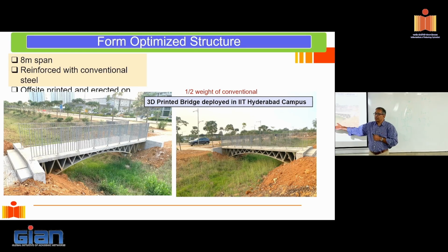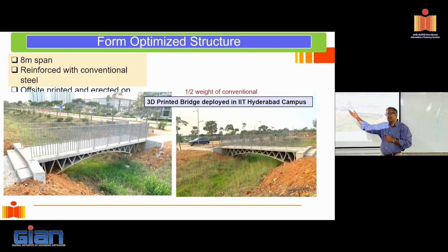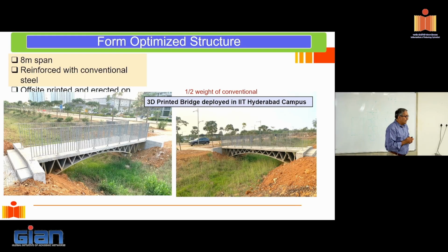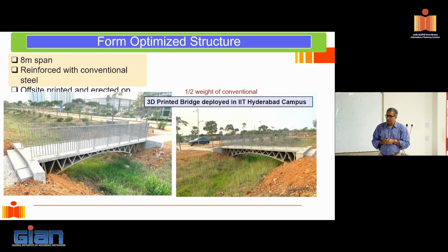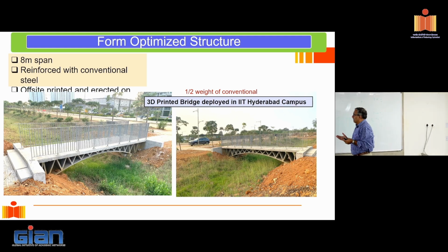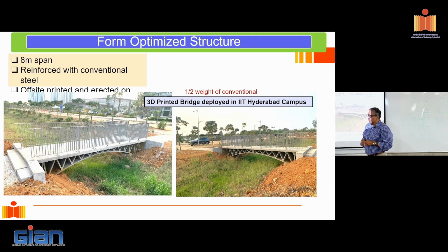Regular concrete, conventional concrete should be 350 to 400. Double or 2.5 times the amount of cement, right? So now we are starting to do the sustainability analysis, the LCA analysis, as we call it. And two things. The LCA analysis shows us that at best we break even. Why? Because I've saved 50% of the material, but I'm using double the cement.